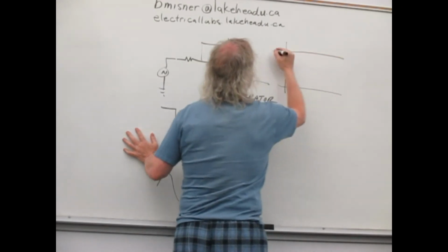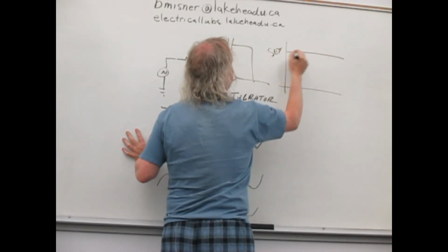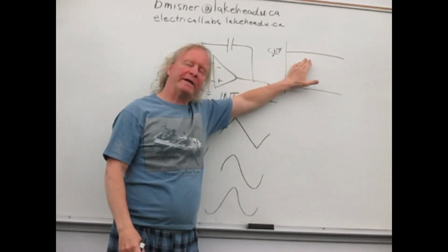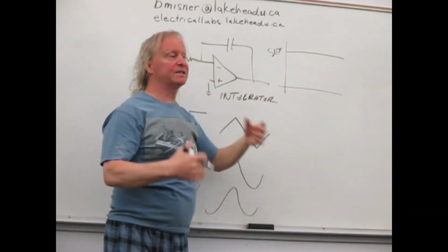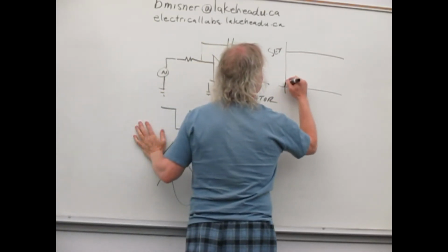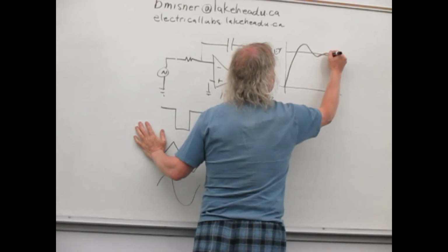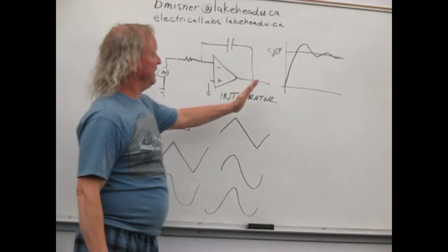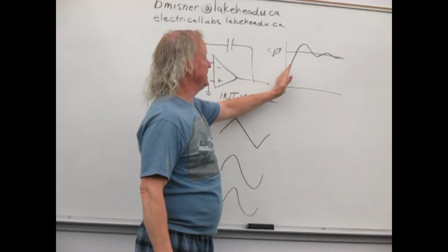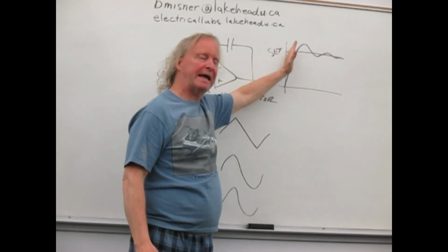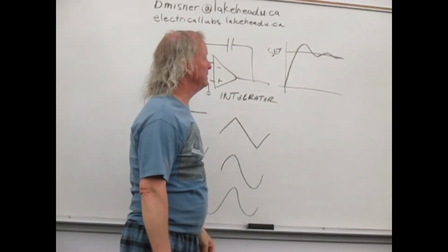So if this is our set point here, right, we want to get to this set point as quickly as possible. And what they say is the fastest way to do that is use this quarter amplitude decay, and the response looks something like this, right? So the proportional is primarily giving this. The derivative can have some effect here as well.